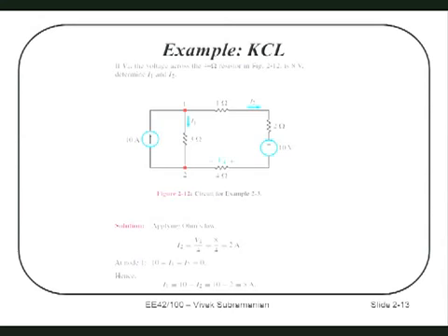For which one? The 2 ohm is 10 volts? This 2 ohms? The voltage across that is not 10 volts. Why do you say that's 10 volts? Let's think about it. Let's figure out what was wrong with that point. Sure, but it's 10 volts between here and here. Right? The voltage between here and here is not 10 volts.